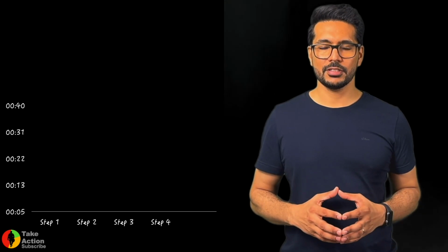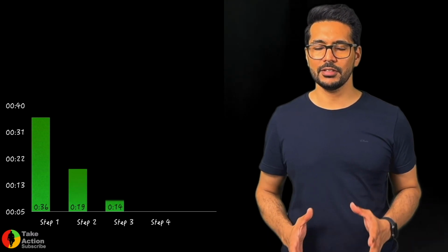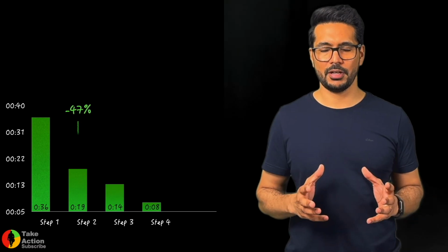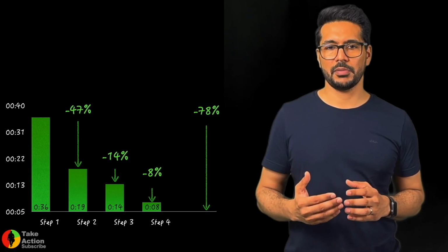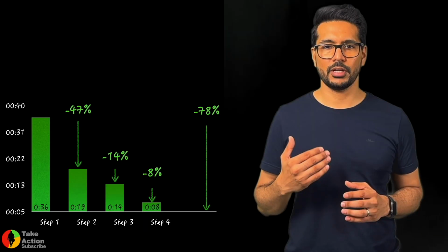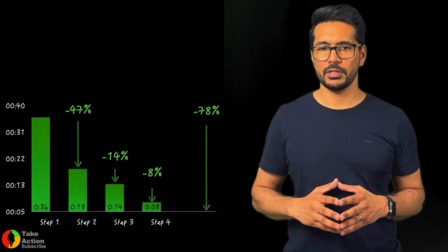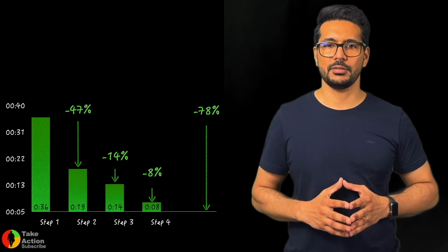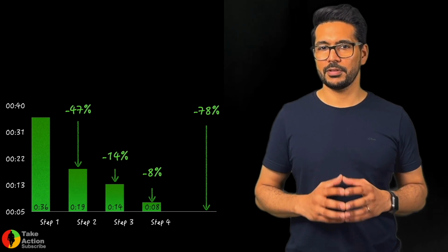So in the end, we can see here the results. After applying this SMED method, we could reduce the total setup time by approximately 80%. And this was the first time implementation. You can apply this method two or three times again after a few months, and you can really harness the benefit of using this very effective yet simple lean tool.